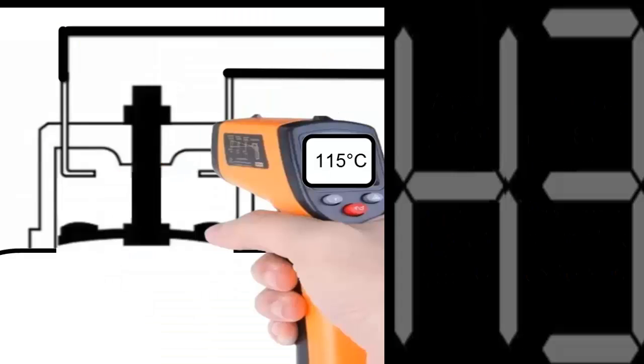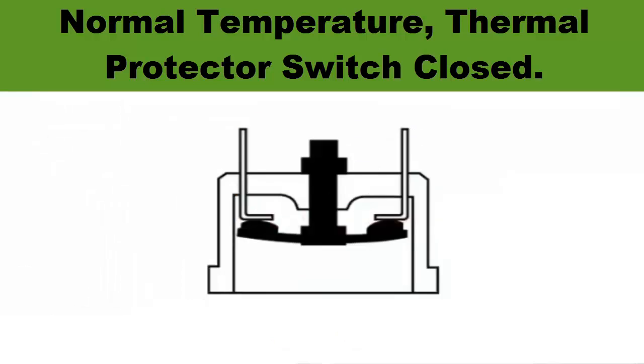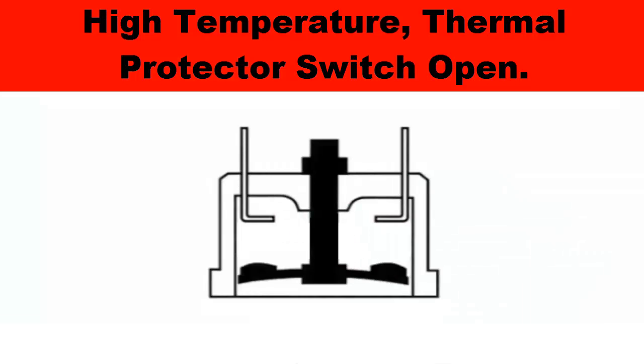7. Temperature cut verification. With the thermostat out of the compressor, increase the room temperature so that the thermostat works and deactivates. If the thermostat does not turn off when it reaches 115 degrees Celsius, then it is defective.